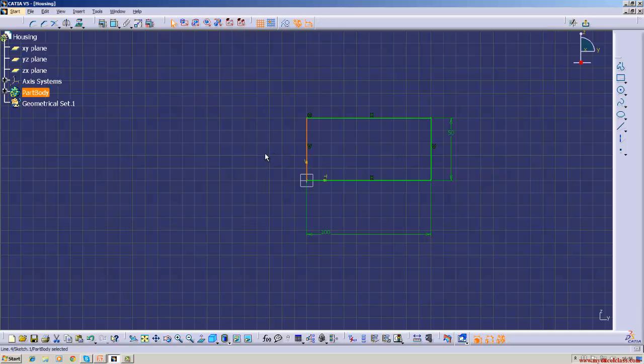This is automatically constraint. We need not apply constraint because horizontal, vertical. This is horizontal constraint, the vertical constraint. That means this line will remain horizontal all the time. It will not change. And this line will always remain vertical. So the 90 degrees always maintained. Automatically this line will be constrained with this horizontal and this will be vertical. So there is no necessity.